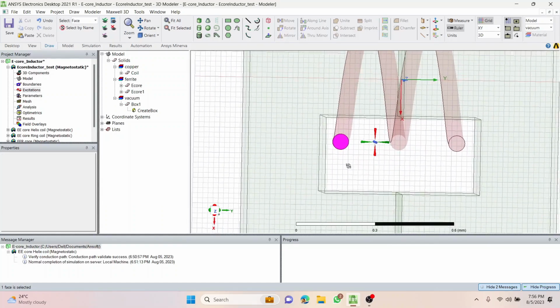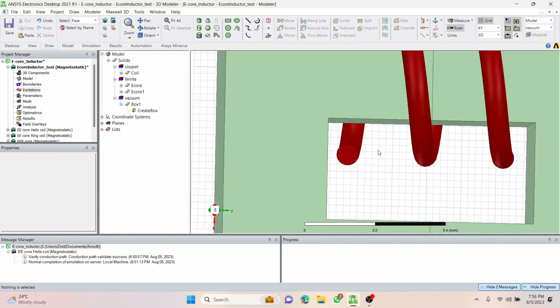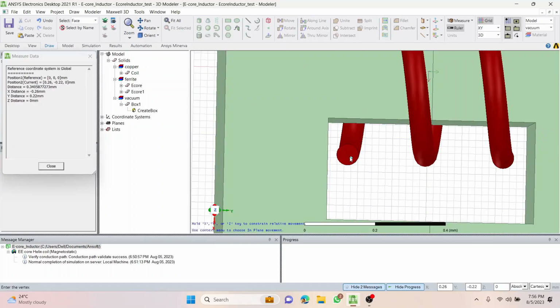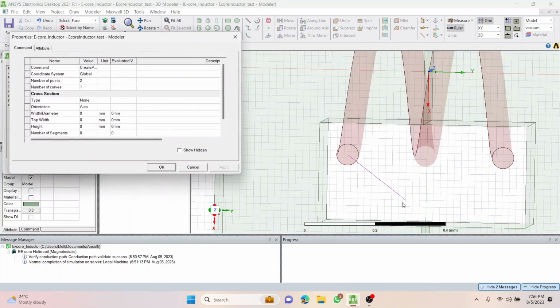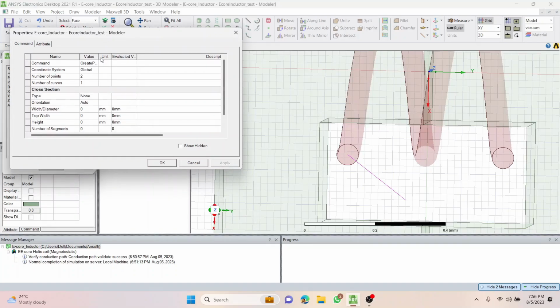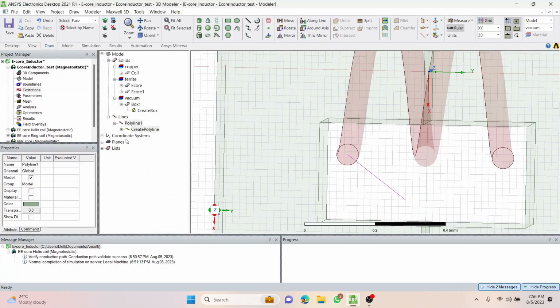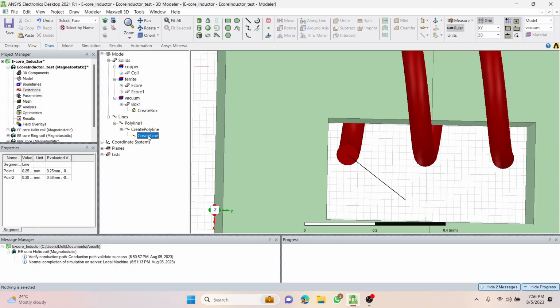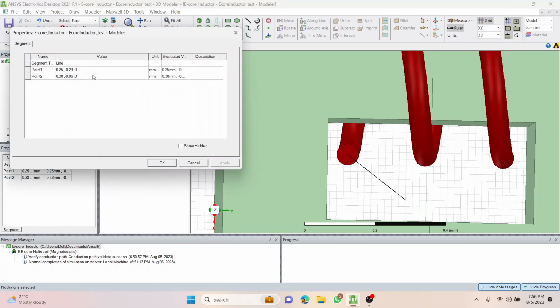So let's just start to draw the extension. Now we know how to draw that. We'll just press the line segment, hover around, detect the center, bring in one line segment, double click it. Now after clicking here, it will create a line segment, create line. So this is the line. The center is okay, right? That means the first point is definitely fine.